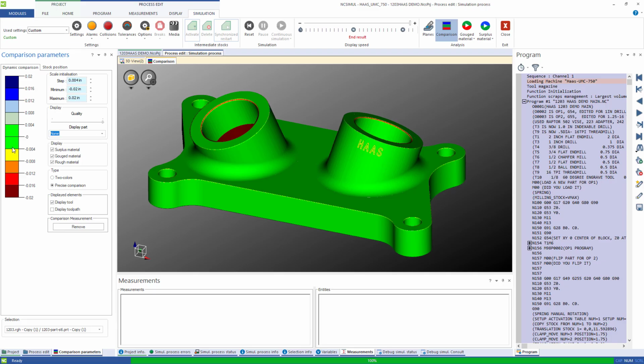And all of these are customizable, so if I wanted to set my step maybe plus or minus 4 thou in my green area, I just add that to that, and it creates the scale based on there. But if you didn't want your scale to be completely uniform, I can also drag any of these fields directly in here to make them larger or smaller for each area.